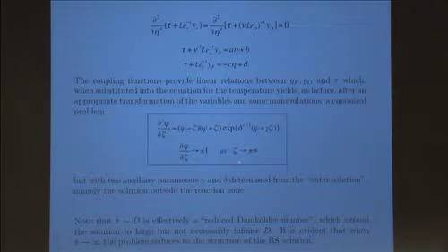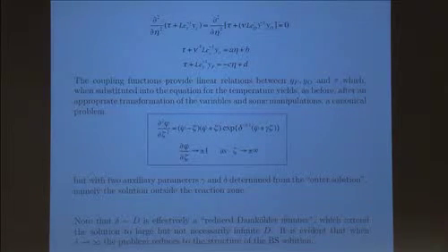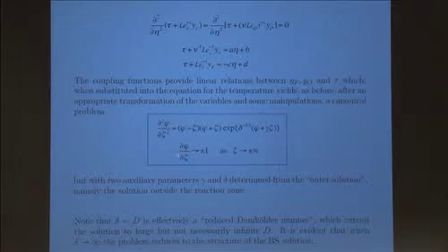Again, it's a canonical problem, but now it depends on two parameters, delta and gamma. Okay? It depends on these two parameters, and this is the canonical problem that you have to solve that describes the reaction zone, the variation in temperature in the reaction zone. Now, again, it has to satisfy matching conditions, and these are the matching conditions. The slope has to go to plus or minus 1.